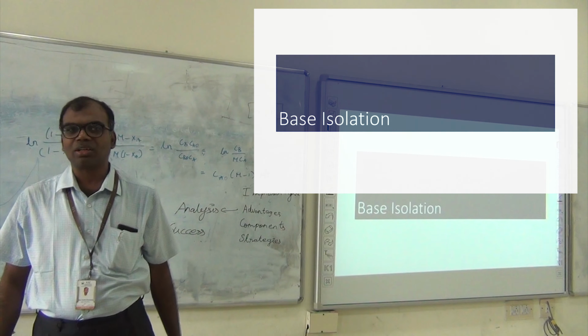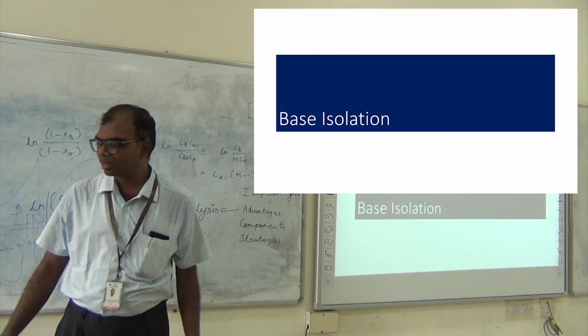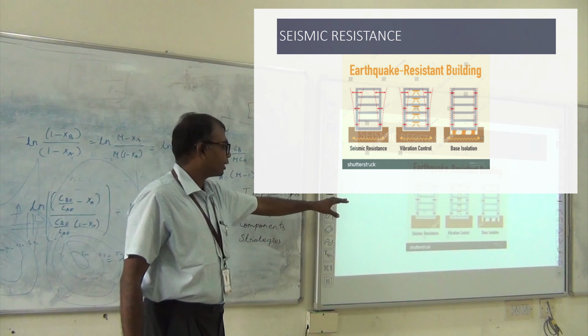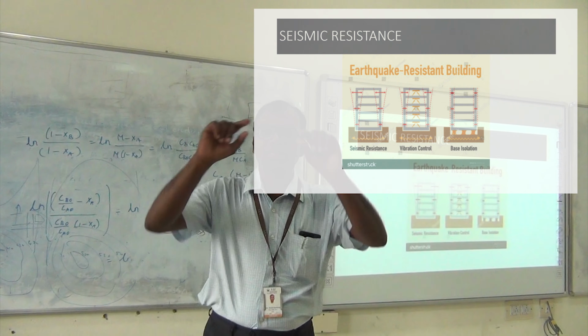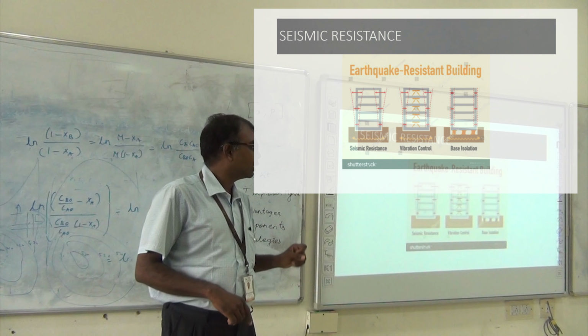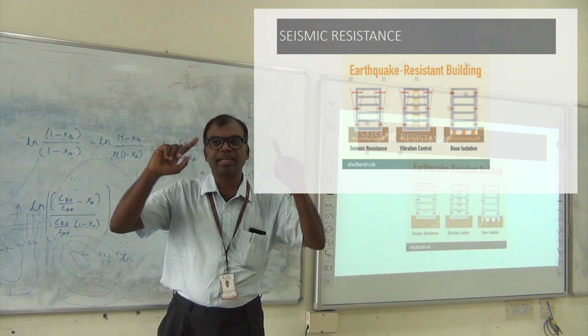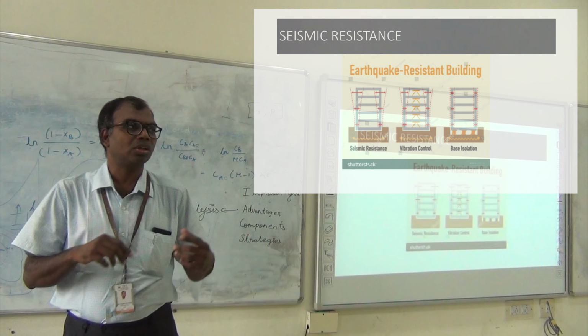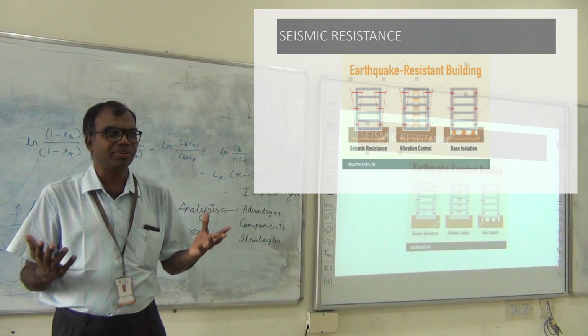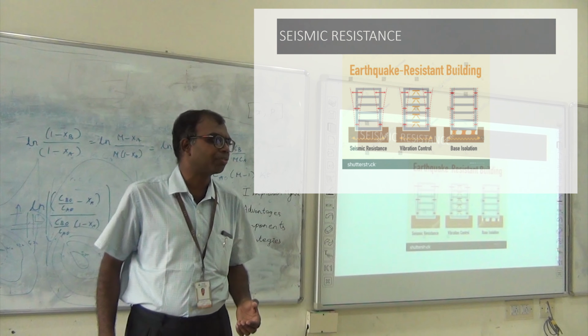Not new, it's a concept which has been there for a very long time, but we have not introduced it in our class. First thing we did was to see whether the structural frame itself is strong enough to take the earthquake forces. Second thing we saw, we can change the stiffness or the location of mass, and then we can cause a benefit, where it reduces the effect of the earthquake.